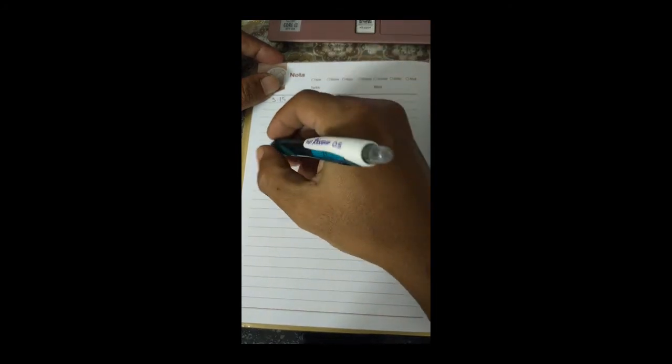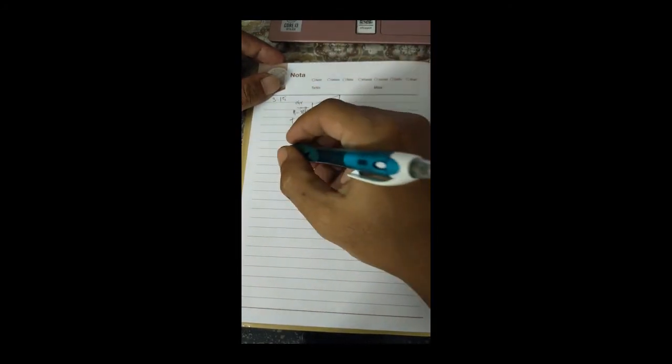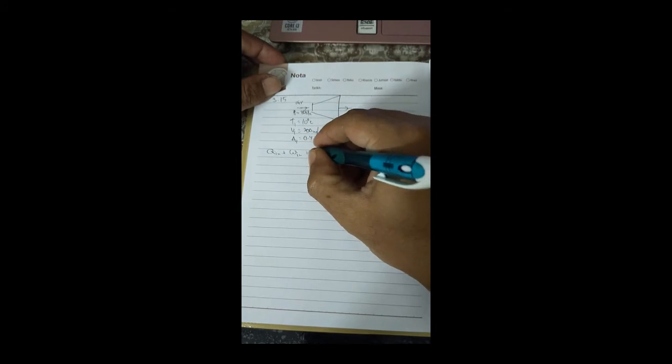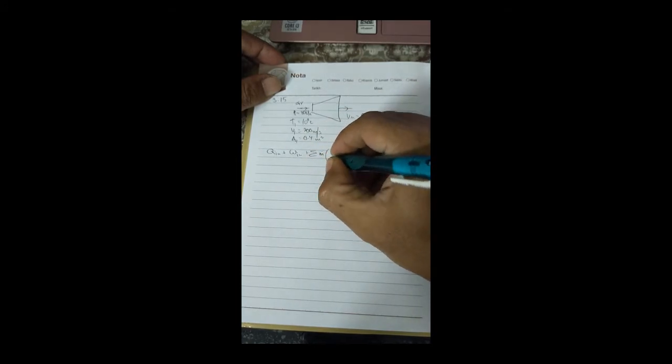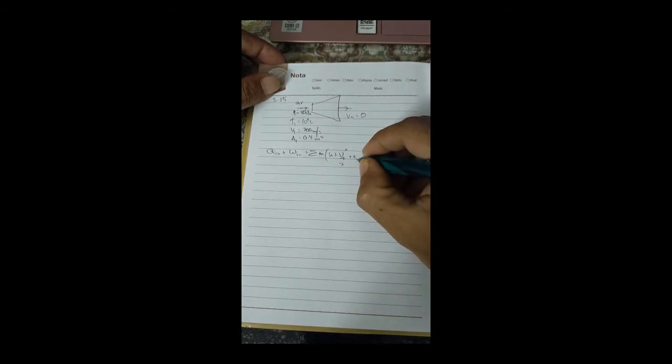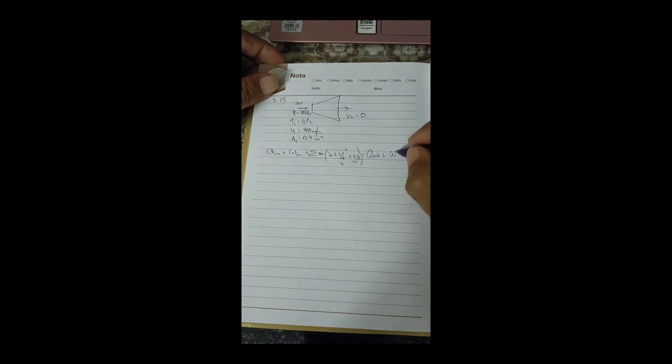Okay, so write your general equation. So Q in plus work in plus summation of mass times enthalpy plus velocity V1 squared over 2, this is velocity, not volume, plus potential energy gZ is equal to Q out plus work out plus summation of mass times enthalpy 2 plus V2 squared over 2 plus gZ.